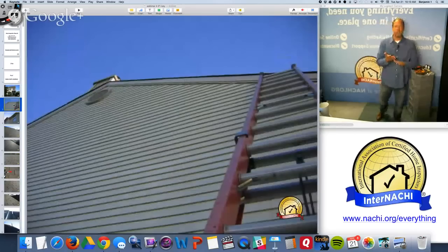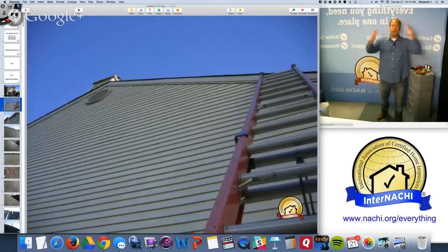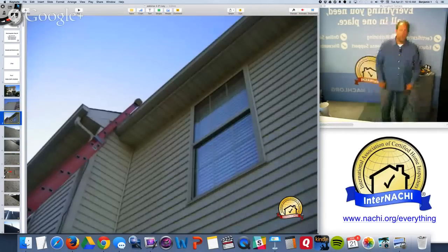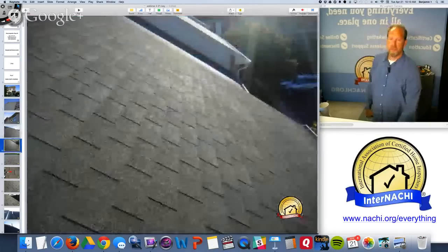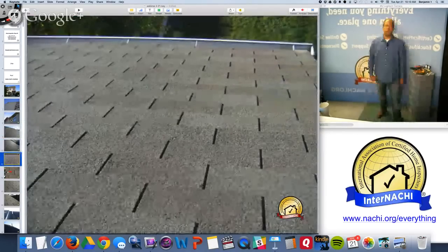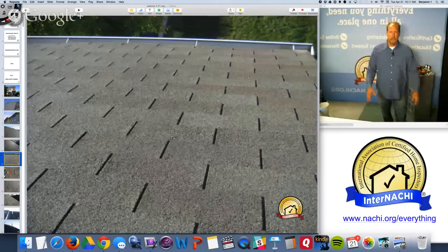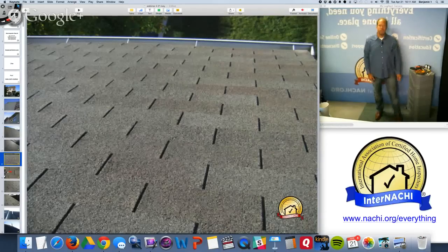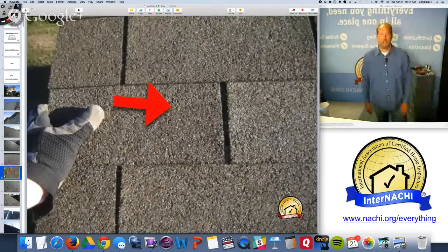granular surface won't adhere. So I bring up my 28-foot fiberglass ladder, and I stick it on different sides of this roof. And I explain to my client why I can't get up upon the roof, but from what advantages did I inspect the roof from? So I'll put my ladder up against the roof, and I take pictures. I take at least 50 to 100 pictures just about the roof. Every roof plane, every roof intersection, valley, ridge, edges, anything that penetrates the roof covering material, I'm taking pictures of it, and close-up shots like this.